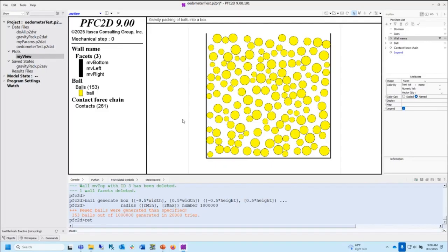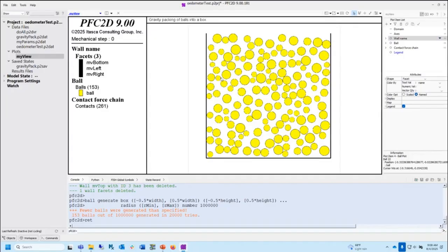You almost never use it. But it's going to keep randomly taking balls and trying to throw them in here so they don't overlap. And this is the best it could do because they can't overlap. So that's what we get. And it's just a uniform distribution. Okay. Normally, we talked about this before. We use the distribute command, and then you can actually specify a completely general size distribution. However, the balls will overlap then, and so you have to let them rearrange when you do that.